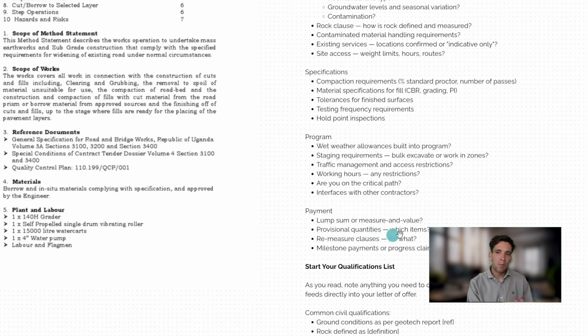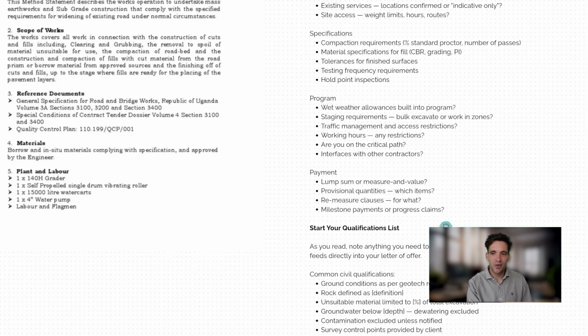And the next would be any sort of payment terms. Is your price based on the bill of quantities? So are you giving unit rates based on an indicative volume? People often like this because it takes out the quantity risk, but the big risk this introduces is the quantity is much lower than you expected. So what you've priced your productivity on ends up being incorrect. So if it's any sort of bill of quantities or remeasurable work, you should always specify a minimum quantity in the work.